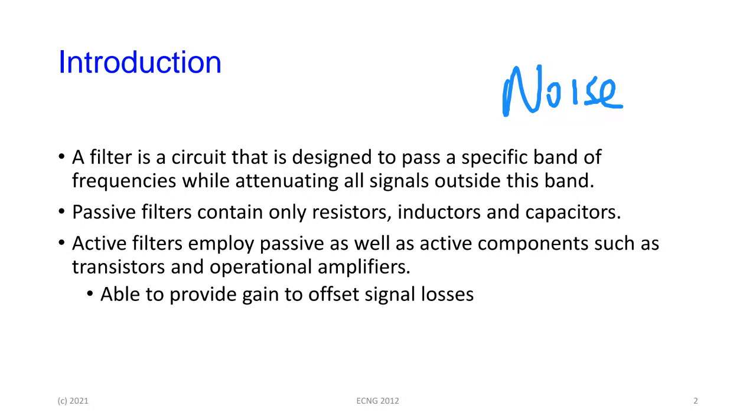Passive filters, now there are two flavors of this. The passive filters only contain resistors, inductors, and capacitors. So your basic RLC network, in whatever combination, series, parallel, or both, as you analyze them, will have a response to some frequencies. It would pass some, and others it would not allow to pass. The thing with passive filters is that the signal that it eventually allows to pass is usually quite significantly attenuated, especially if the filter is a large filter. We'll talk about what you call a large filter in a little while. So if there's an alternative to doing that, it is preferred.